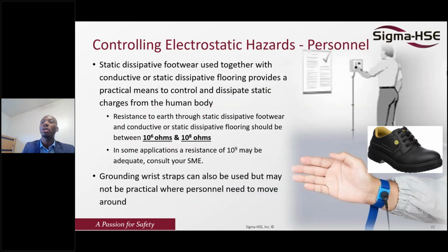So how do we ensure that the operators are bonded and grounded? The first one is using footwear. So you can see this one. Normally, most of them have a yellow tag. You can see the picture, the middle picture on the right, and normally it indicates ESD. So anytime you are working in a flammable atmosphere area, we need to ensure that you have static dissipative shoes.